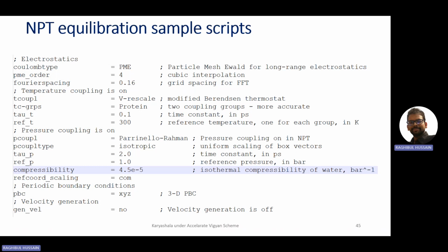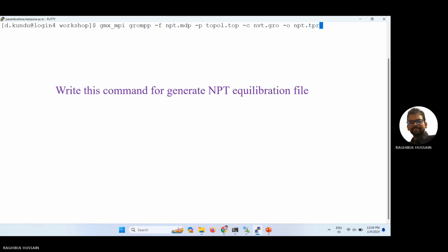And try to run this one. One correction: for the system that we have done, we used gmx_mpi, the MPI parallel version. There might be no parallel computing available in your system. So write only gmx, don't write the space and mpi. Just leave that out. Write gmx. It will not create any problem. Just gmx.